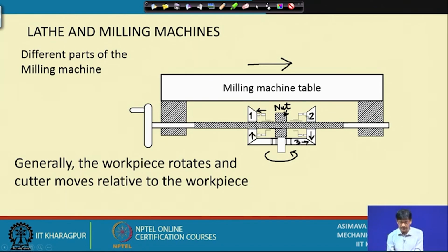So, you can clearly see the directions of rotation of 1 and 2 are opposite. So, if this clutch clutches onto 1, it transfers motion from 1 to the lead screw and the lead screw rotates. So, basically I am bringing in power from the motor, I am making 3 rotate somehow, and once 3 is rotating, 1 and 2 rotate, but they are not intimately connected with the lead screw.